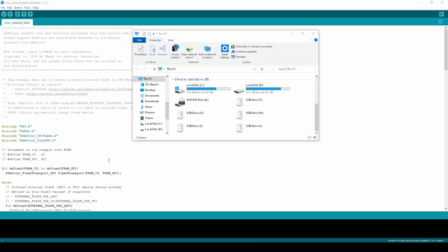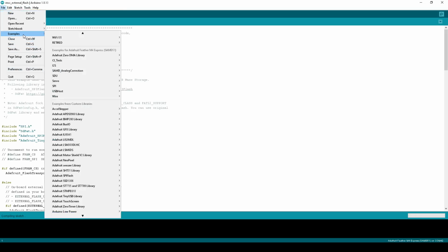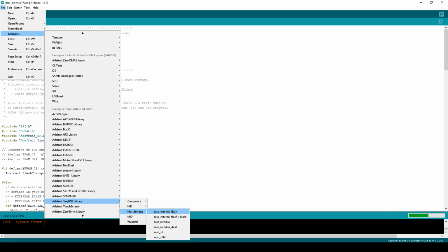You can view the files on an Arduino SPI flash through the USB port. So you can upload the TinyUSB example code, examples TinyUSB in mass storage, and this will expose the SPI flash as a USB drive, so you can upload stuff to the SPI flash and access it in Arduino or in CircuitPython.